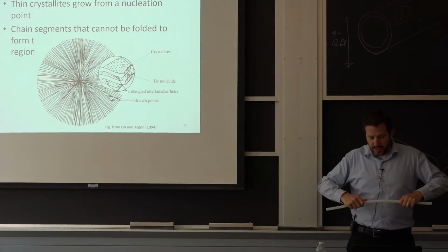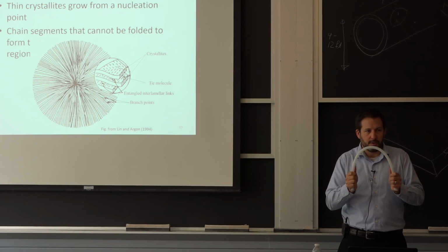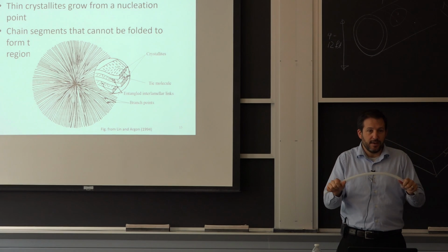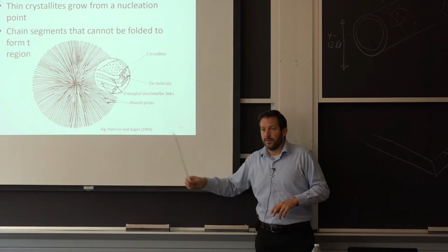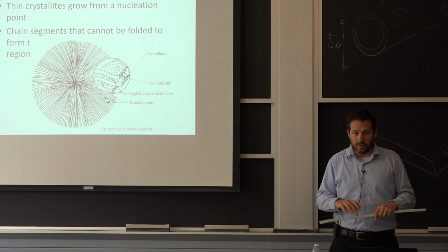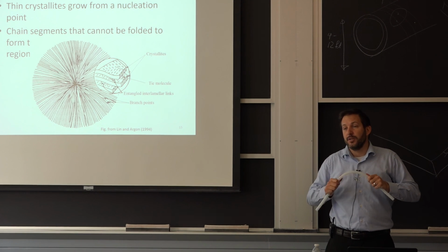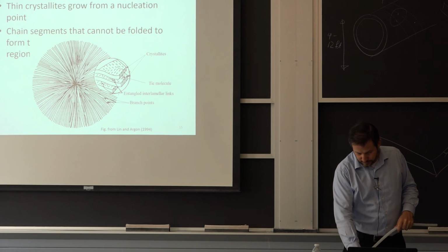So there's going to be a limit on how much you're going to have this before the crystals become unhappy. Polycarbonate, for example, does not have a spherulite structure. It's perfectly amorphous. It's just randomly organized throughout, and that's why I get a lot more deformation before anything happens to it.